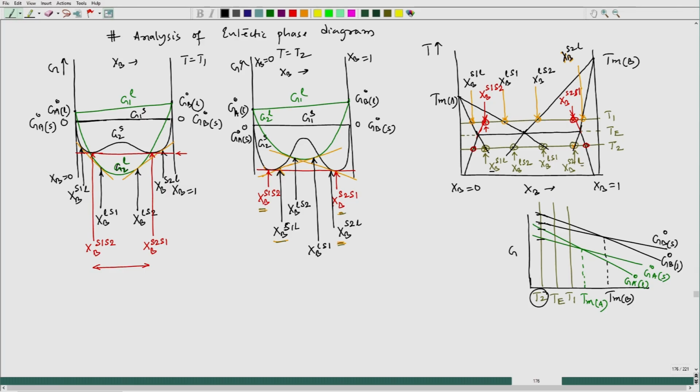If you recall, in the case of a single component system, we extended the stable equilibrium line into another phase with the help of a dotted line. So, here also, since those compositions are metastable, as we have marked them above the stable compositions falling on the common tangent, those compositions can be shown with dotted lines in the eutectic phase diagram also.